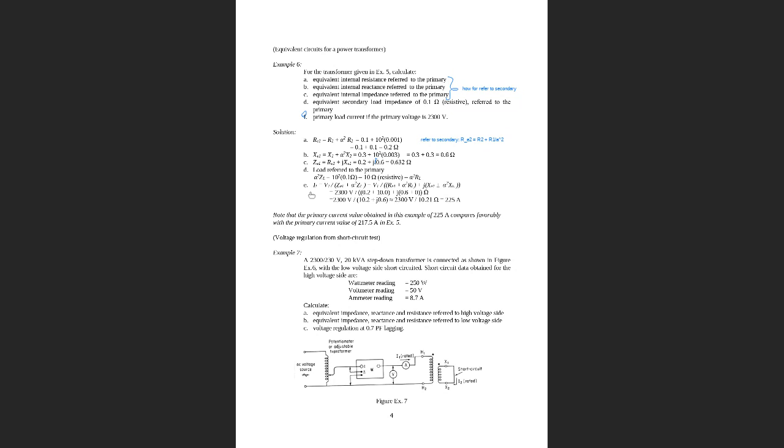Given that the secondary loading impedance is 0.1 ohms, when referred to primary it becomes 10 ohms, which is resistive.